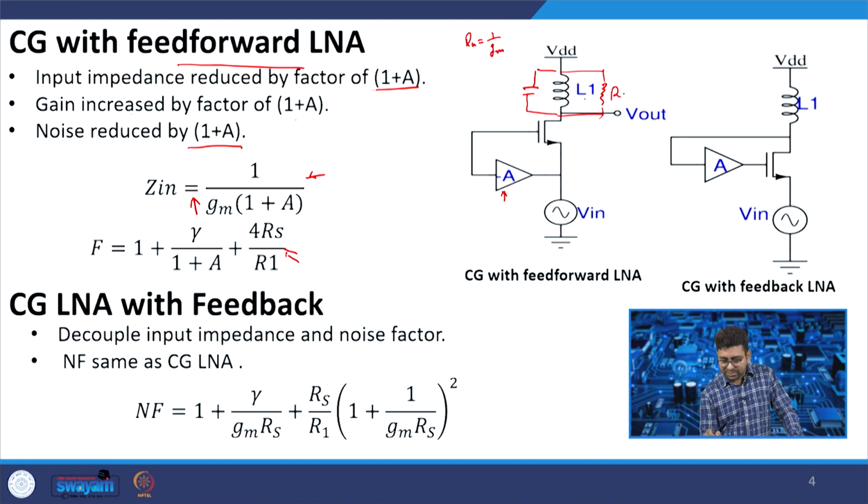So, there is a resistance R1, and during the resonance that resistance will be there. We can also keep a separate high value resistance in order to get the higher gain. However, it will suffer in terms of your quality factor, which means your noise will increase.